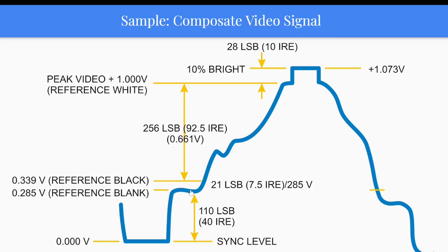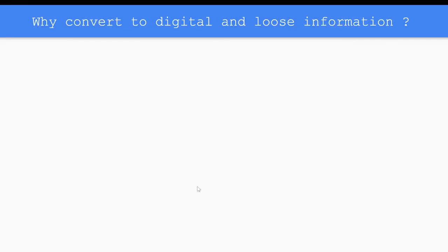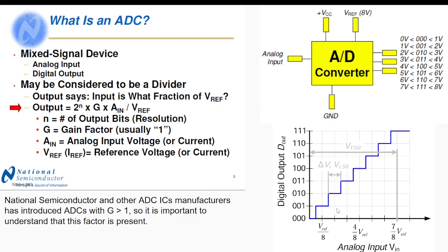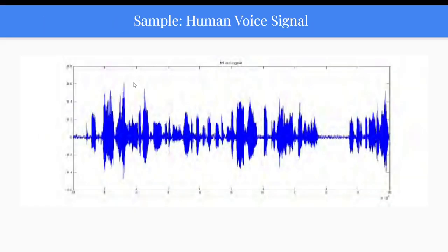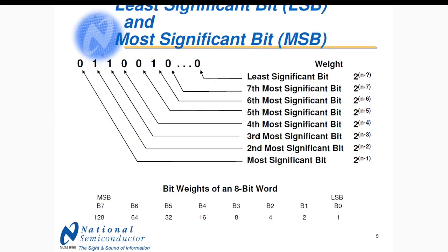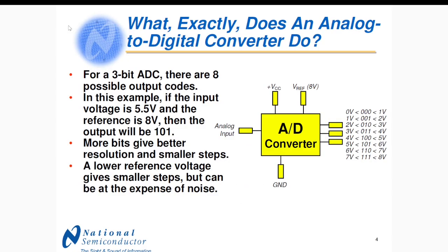And what is the reason behind that? Because if we go back here, let's say that this is our noise level, and we are going to do a smaller step like this. The thing is, we are very near to the noise. That's what it means, because we are talking about analog input. So depending on your environment and what you want to do, these are very important and powerful concepts. Okay, so let's carry on to the next slide.